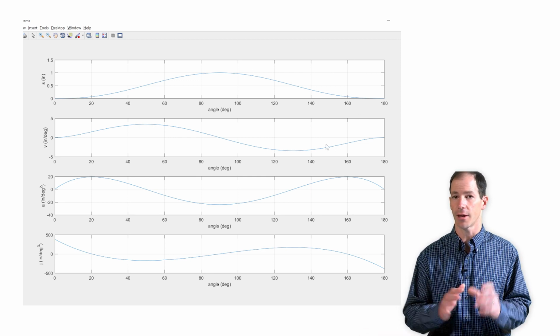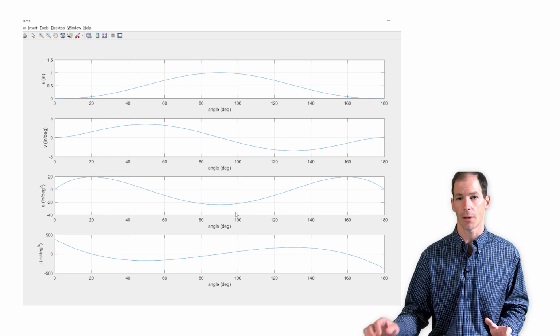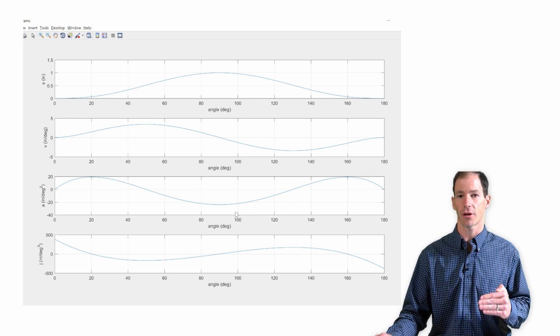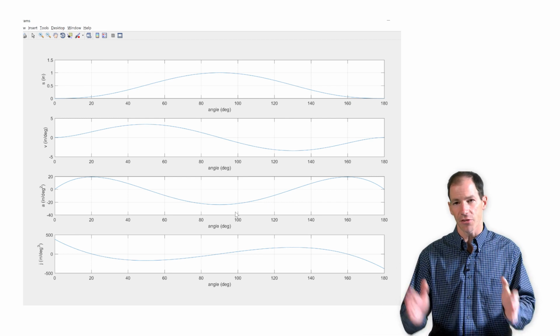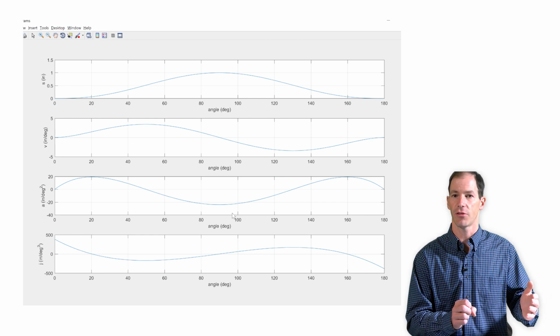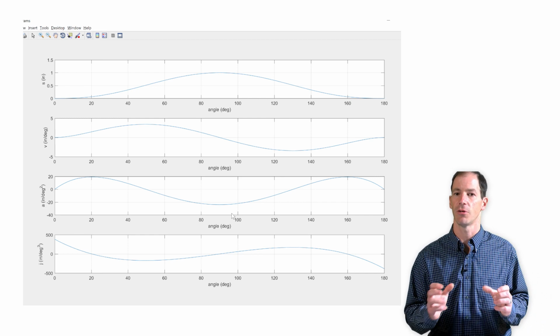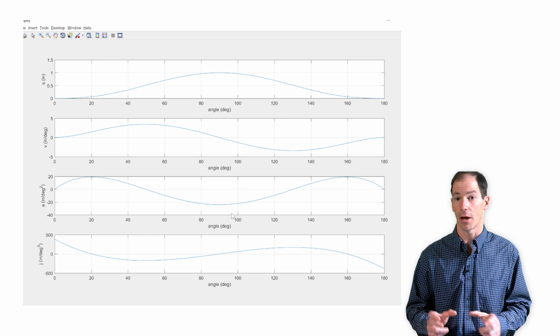If I can do that, then I'm satisfying the fundamental law of cam design, and I can get good cam functions. So let's say that we're matching a conveyor belt. I'm moving at a constant velocity for one segment of it. Well, the segments coming into that better have the same velocity matching and the acceleration set to 0 if I have constant velocity. So we just have to be careful with that as we design these segments of polynomials to put together to create more complex cams.